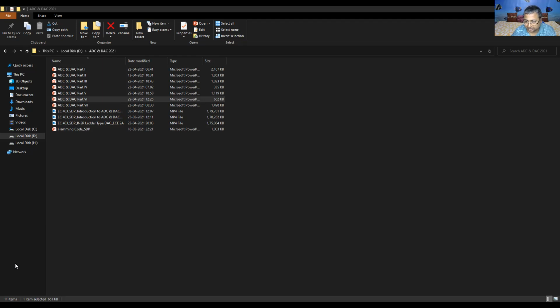There are two slopes. One is the negative slope when it is connected to V in, the integrator output, and this is the positive slope where the integrator output slope is positive, connected to minus VR. Okay, so minus of minus VR, that means plus VR.